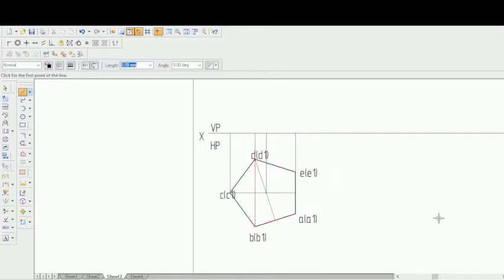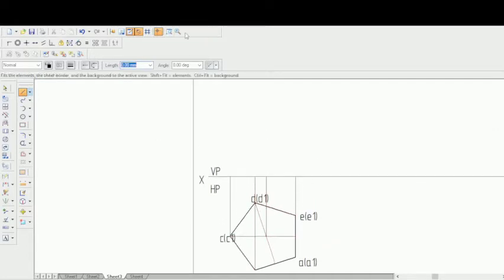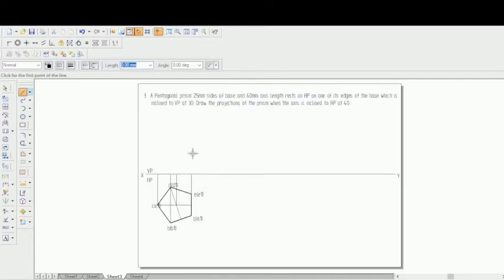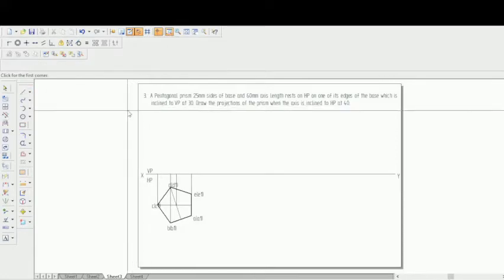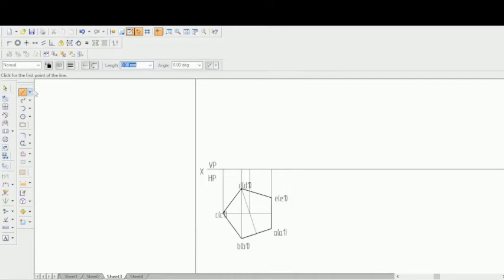So okay, now this is the center one. This is the center, I mean it's like the axis line. It is clearly mentioned in the problem that the axis length is 60. So let's try to zoom it again. You can try to zoom it and keep drawing it every time. So let's go to a center line. From here, let's give the axis length as 60.